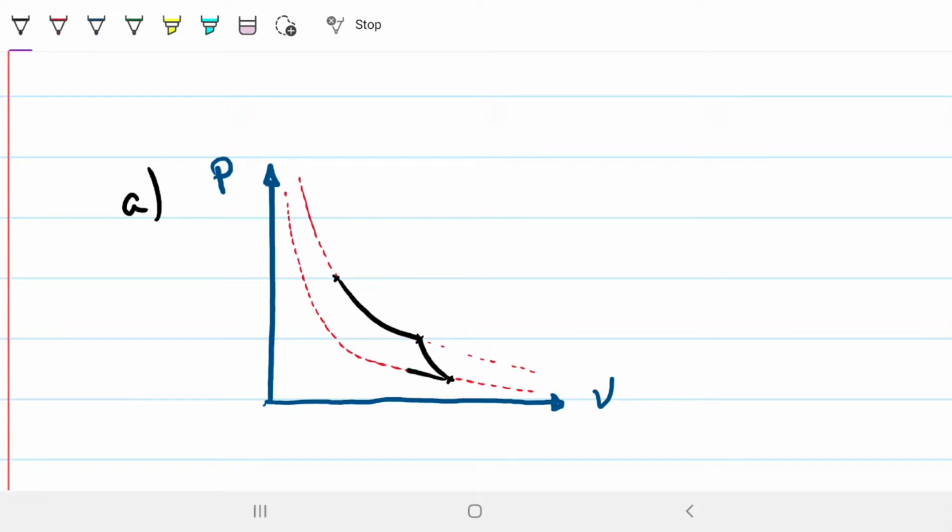One of them is going to be along this dotted line again, because this is an isothermal process. And then we stop somewhere here, and then we have a bit more of a compression, but now isentropic compression, right? So something like, oops, it was too much. So something like this. Okay, so we're going in this direction. And we have state 1, I'm going to call this one state 2, state 3 down here, and then state 4 down here too.